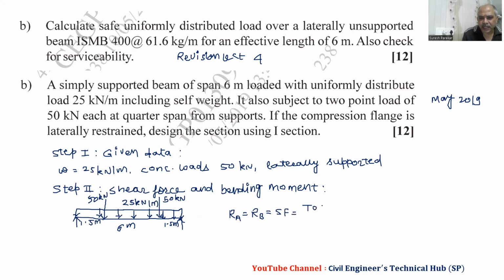Since it is symmetrical, we have total load by 2. Total load is 25 into 6 plus 2 into 50, divided by 2, and it comes 125 kilonewton. Now this is the reaction. Maximum bending moment will be at the center, that is 3 meters from here.